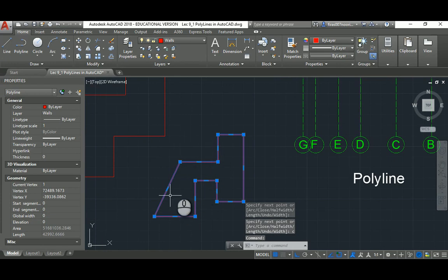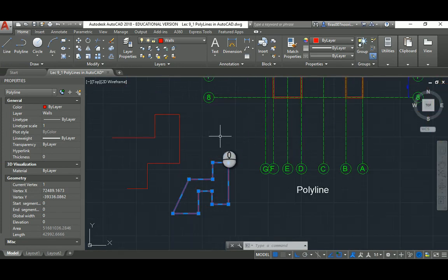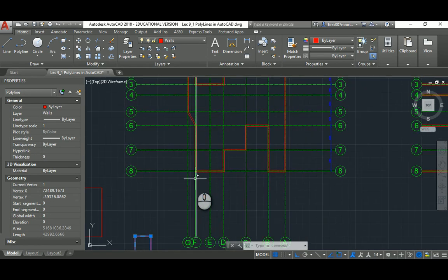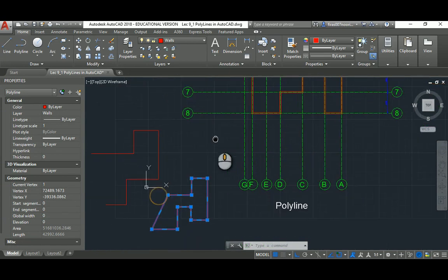And when you send this to 3D Studio Max and then apply extrude to create a fully enclosed geometry, you can generate area for it. You can use it for hatch on boundary here inside AutoCAD also. So polyline is really important to create and to understand the areas of an object, making a hatch, defining a specific area of a building or specific area of a walkway or anything else you want.